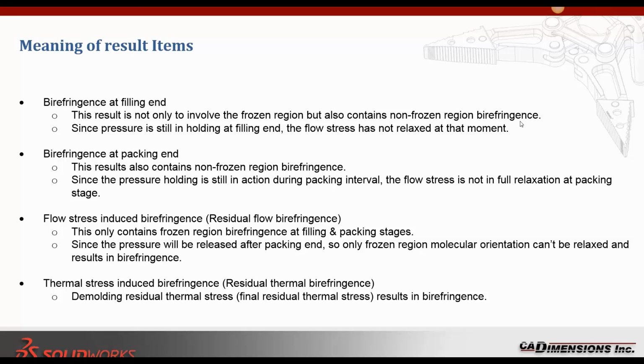Because it is before the pack hold phase, before the plastic completely solidifies. Birefringence at packing end results also contain non-frozen region birefringence. Flow stress induced birefringence only contains frozen region at filling and packing stages.